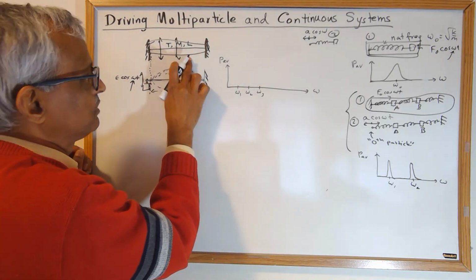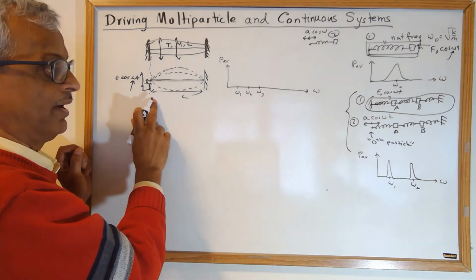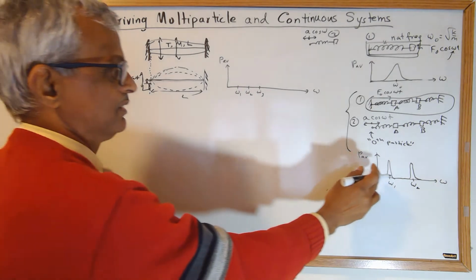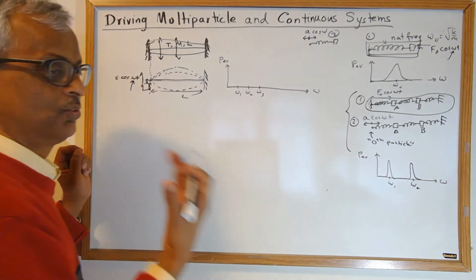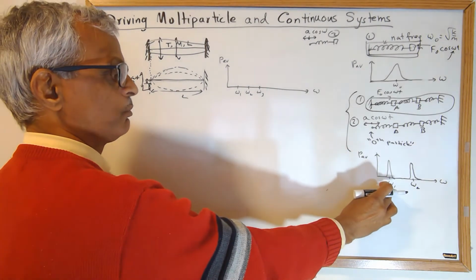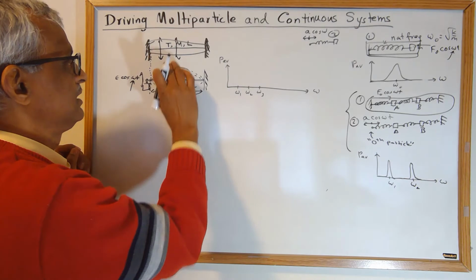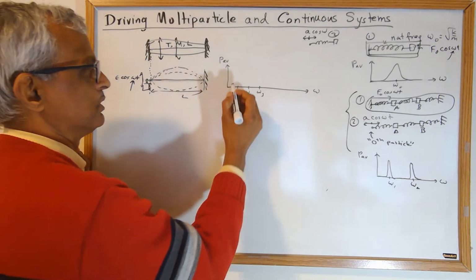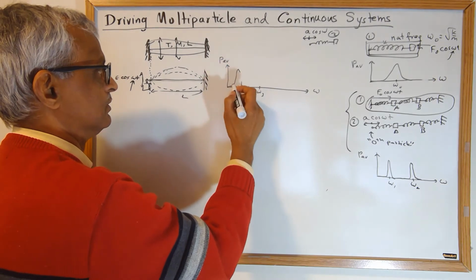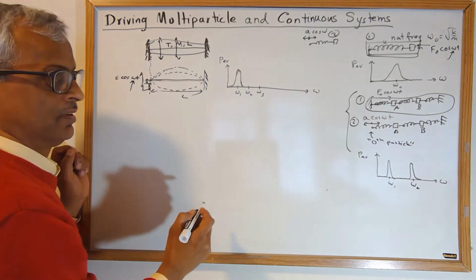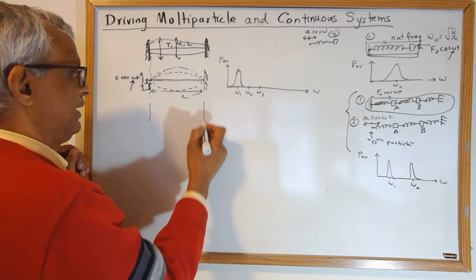Those were the normal modes of that system that I'm trying to so-called excite. When you put energy at the normal modes, we use the words exciting normal mode 1, exciting normal mode 2. So by doing this, I excite this normal mode, and so I'll see a resonance. And I keep increasing the frequency, I will excite the next one.